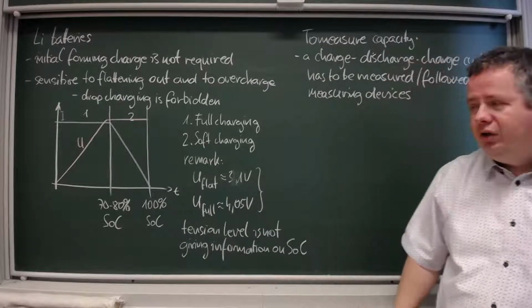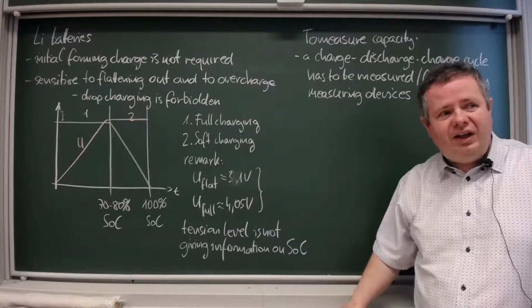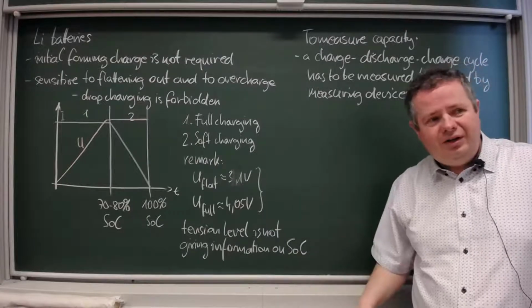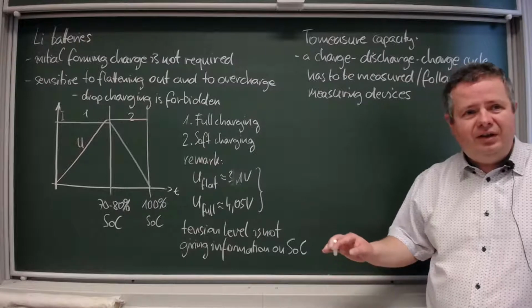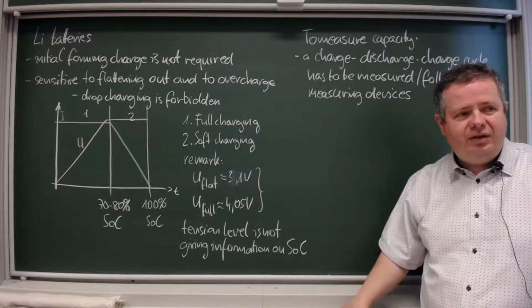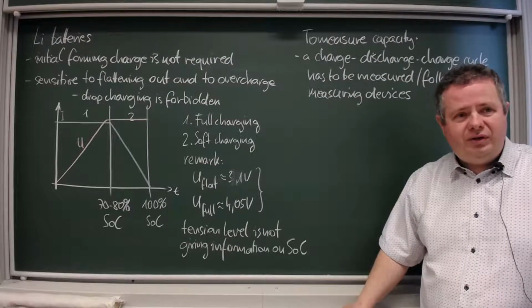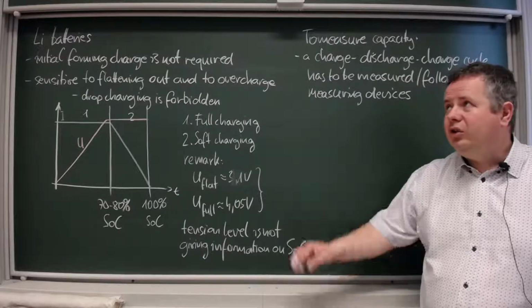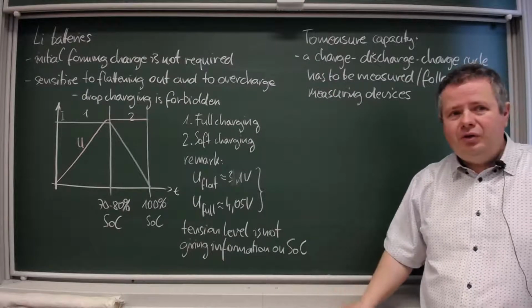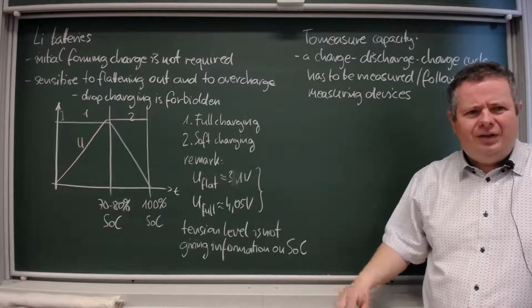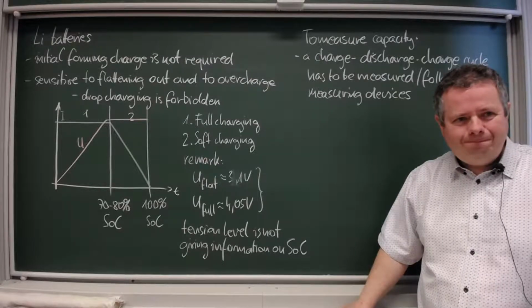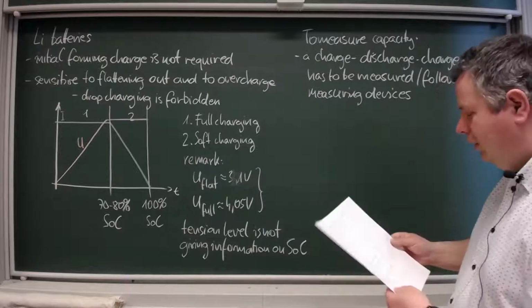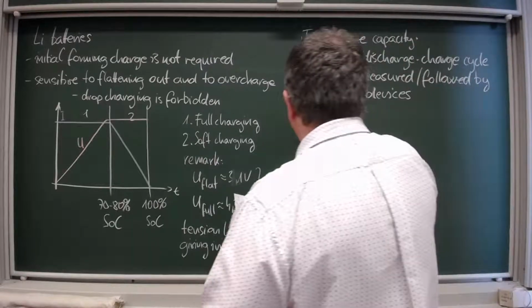So charging: first check your battery type, then check your charger. If the charger can do the type of charge required for the battery type, and if both are okay, then you can plug in and charge your battery. If you get a charger for a lead-acid battery, don't try to charge your lithium cars with it, it won't work. Okay? Good. And now some words about capacitors.